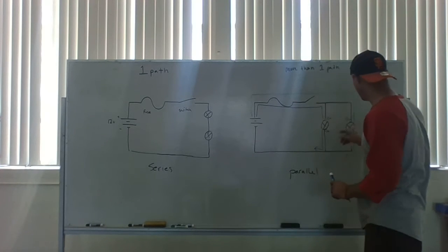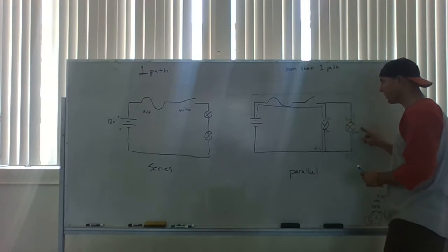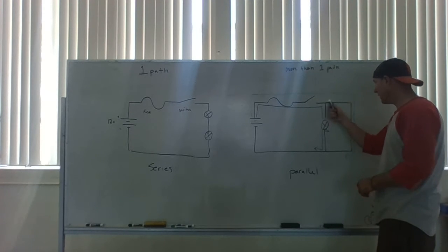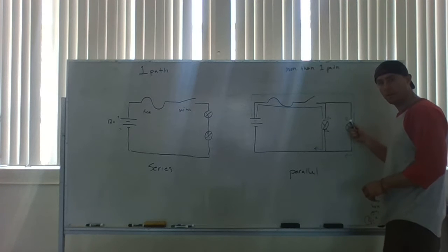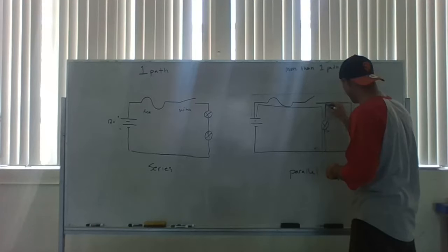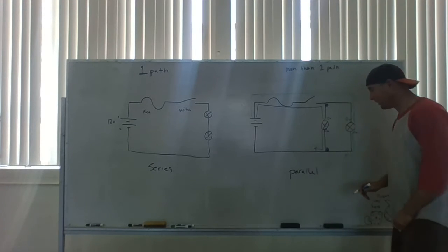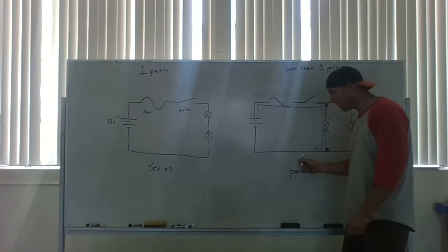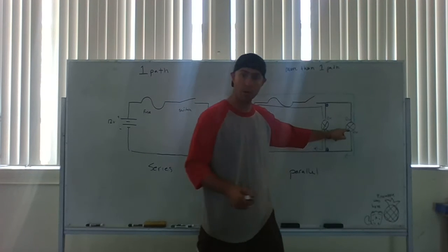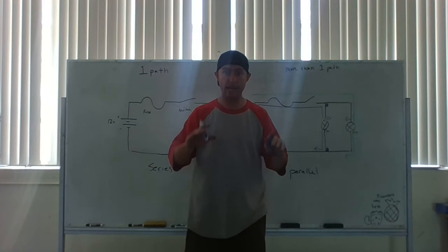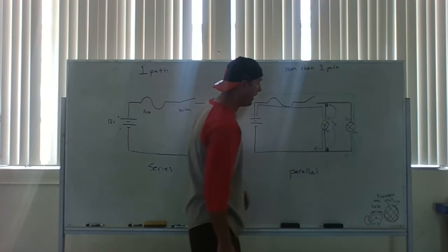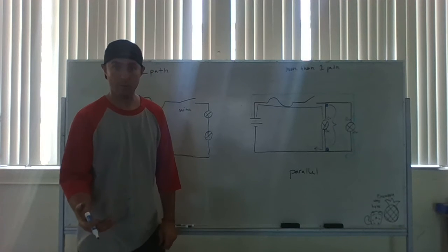So if this bulb is out, but this bulb is working, my power supply side of my circuit is functioning because I'm getting power to this one. That means there's some problem between that connection and that connection, because I also know that my ground path is still working, again because this side is working. So now I've isolated my problem to between these 2 points, which obviously is much easier to troubleshoot.